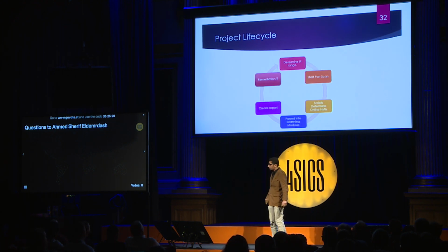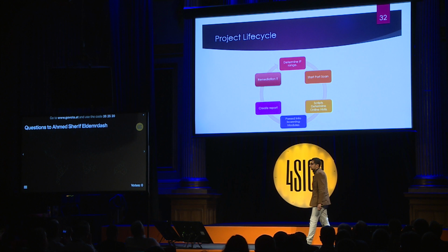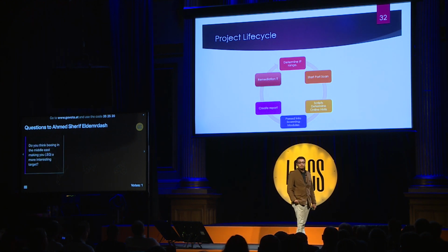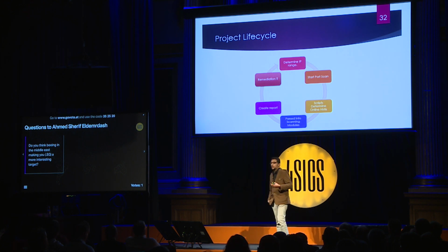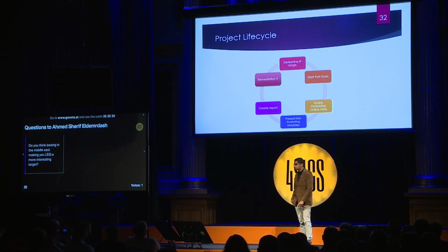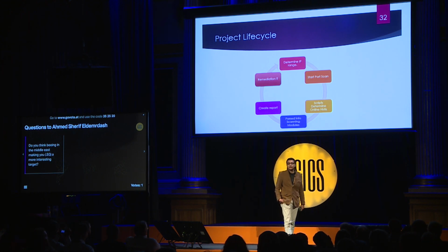So the project life cycle was like this. It started from determining the whole IP range of Egypt, which was about 14 million IP addresses. Then it started port scanning on the industrial control system related ports, and then parsed all of this to Python scripts, which I wrote to identify common HMIs for industrial control systems, and then it makes an alert for us if it identified interconnected SCADA systems in Egypt, so that we contact the organization.